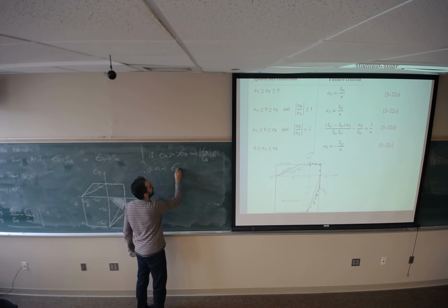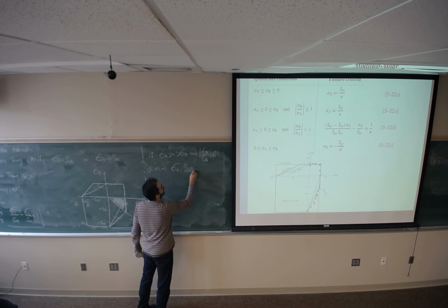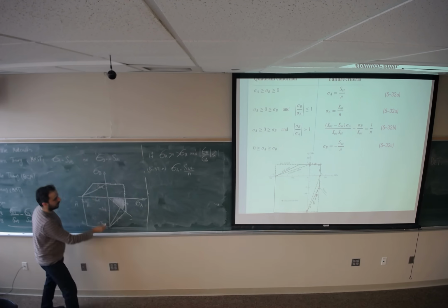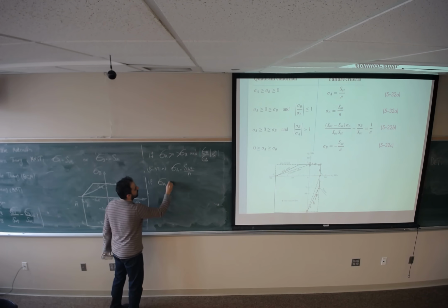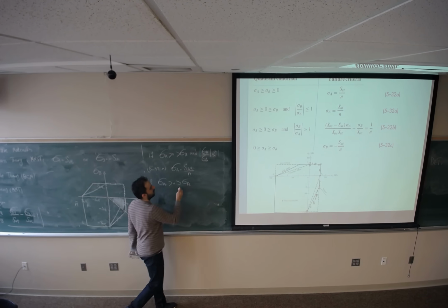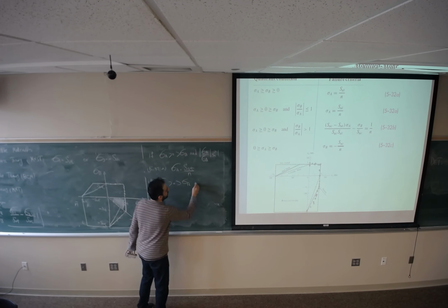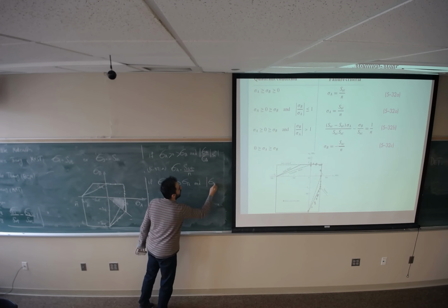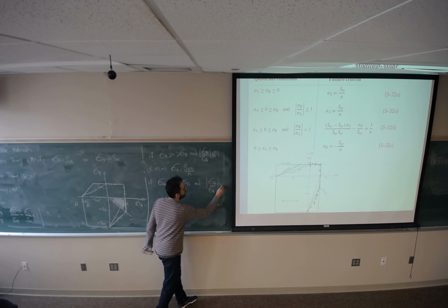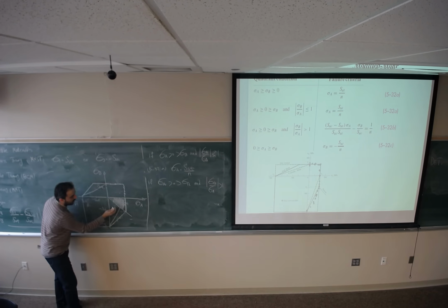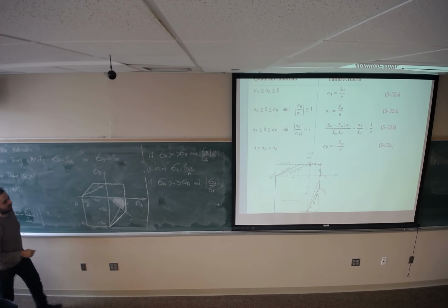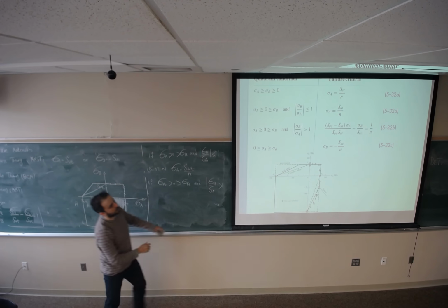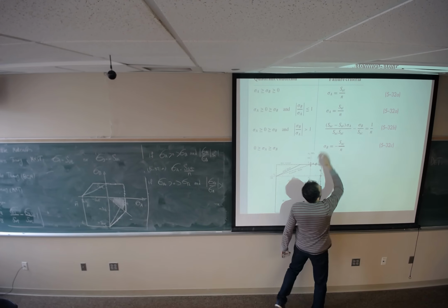Sigma A would be SUT divided by N, if the point is somewhere here. But if sigma A is greater than 0 and sigma B is negative, and sigma B over sigma A is greater than 1, meaning the point is going to be below this line, then we have to use this line as a failure criterion. What would be the equation of this line? Equation 5.32b.